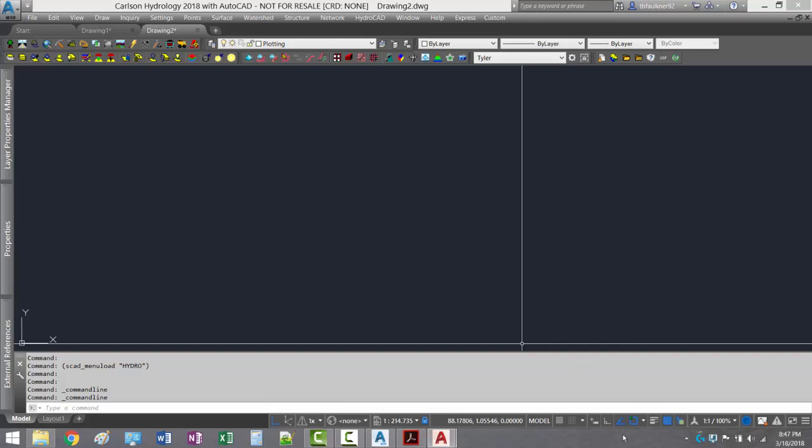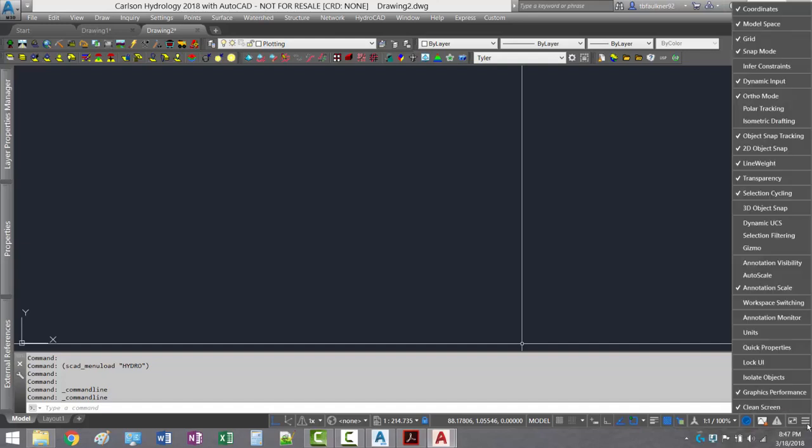But essentially, if something is highlighted in blue, that setting is active. Right now, I'm hovering over my object snap. It means my object snaps are active. If I go all the way over to the far right, I'll see three horizontal lines. You can see there it's popping up, it says customization. If I click on that, this is a menu of everything that I can actually display in the status bar. For example, I've got my dynamic input option, which is this icon right here. It looks like a plus sign with a little tag on it.